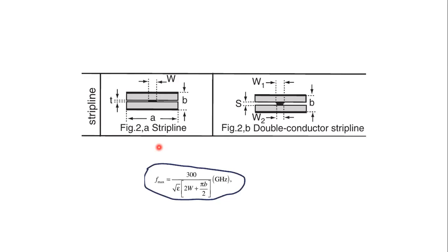If you look at the structure here, this transmission line is simply a modification of your coaxial cable. Coaxial cable is considered to be what? The superior-most transmission line. The simple reason is that it does not have radiation loss. Of course, up to a certain upper frequency, the radiation from the coaxial cable is 0.